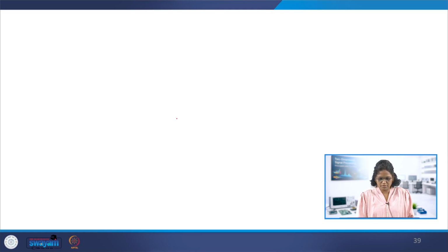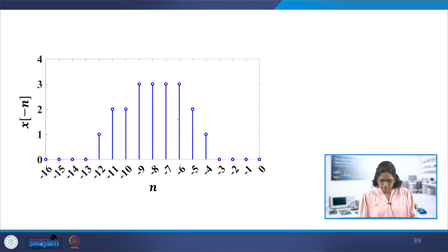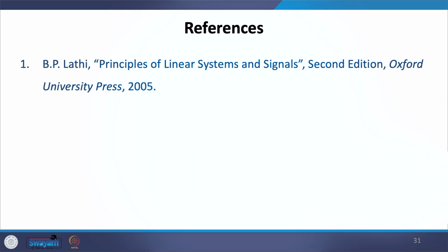It's a flipped signal, the n has become minus, you can see here, and that becomes negative indices, x of minus n. That's a flipped sequence. So we can combine these operations as well, that is time shifting and scaling, also flipping the sequence. How do we do that? These three operations can be combined. Delay, shifting and scaling can be combined, making the operation also.